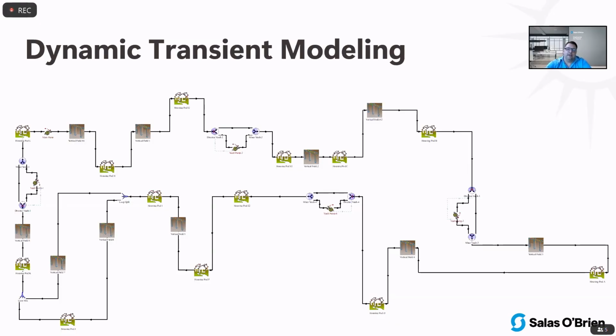And then we can also really look at not just the heat pump efficiencies, we can also dive into the parasitic pump loss efficiencies. One thing you see with these large thermal energy networks is there's a lot of pump energy. The bigger they get, the more pumping you have. And so how much are we being penalized by connecting all this together? Or are there different ways we can do this to maintain small parasitic losses on the pump side, so the cost to operate the system doesn't offset the benefit, as if you were to go through and maybe do these in smaller pieces? So those are all things that we need to really understand and need to model correctly as we're designing these systems.